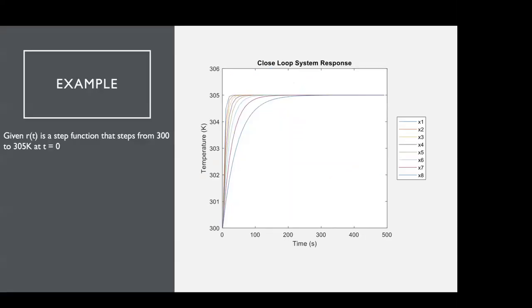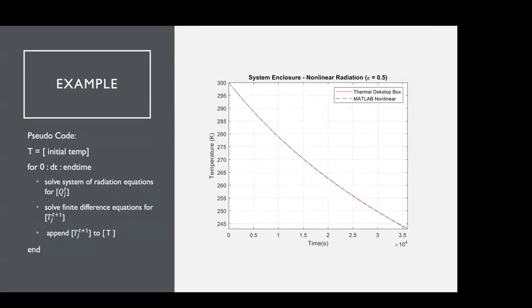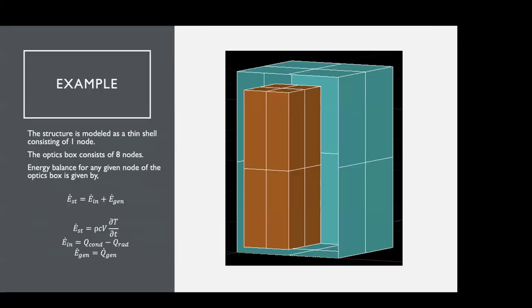That's what the Q generation term is, modeling the heater, and it's attached to each node. Since each node has an input, I can control each state, or each temperature. You write it in the correct form, and you can derive a control law that will drive it to that temperature.